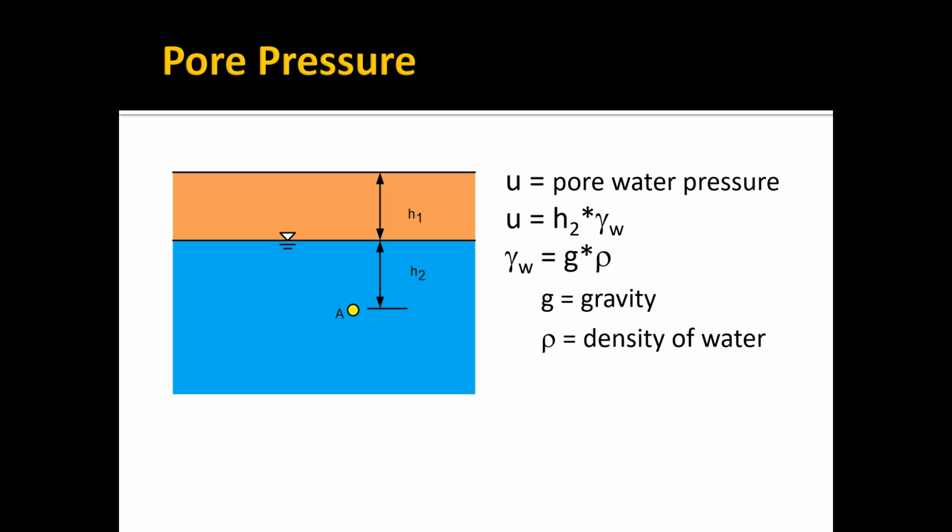Now, in practice, the actual saturated portion of the soil could theoretically be higher than this because of something called capillary action. If you have really small voids in the soil, if it's a fine-grained soil, sometimes the capillary pressures in the soil, which you may remember from chemistry, would pull the water up above the water table.